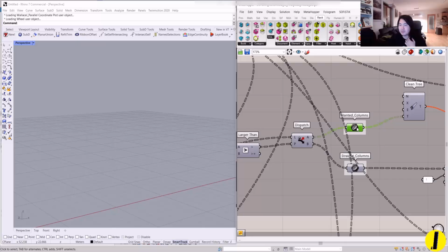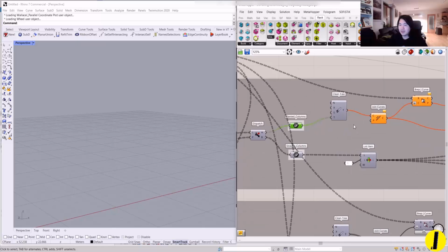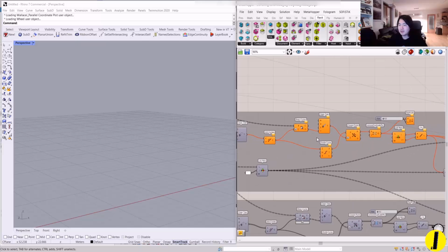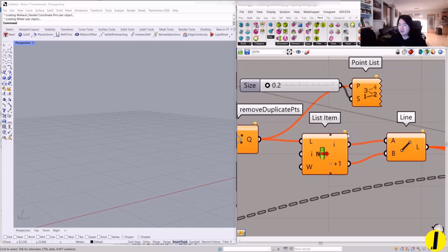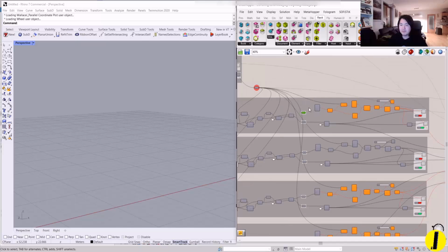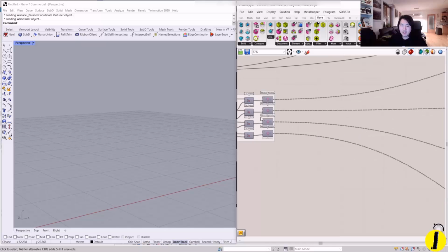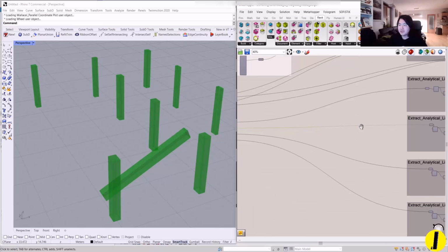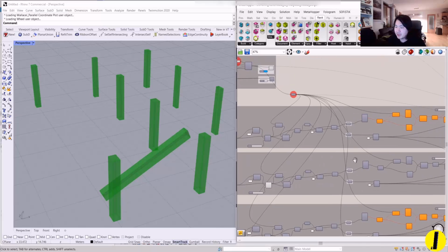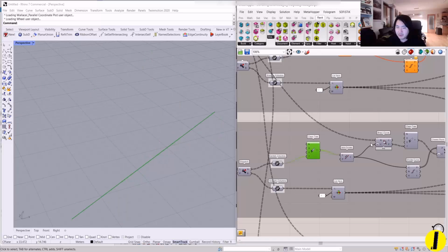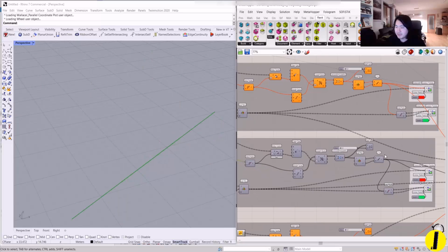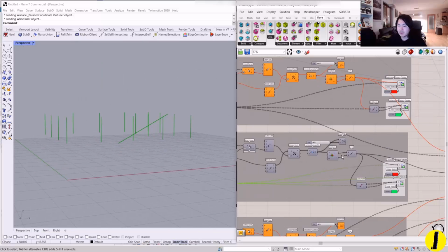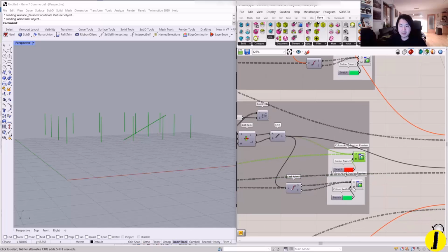If there's a slanted column, you can also get the slanted column data, but right now there's no slanted column for level 1. That's the reason why all the other components are giving warnings, because there is no more input. But if you go to level 2, I put on purpose here one slanted column. So this column is also appearing from this tree here. So we have these components activated. In this case, level 2, we get straight column and slanted column that you can highlight now.